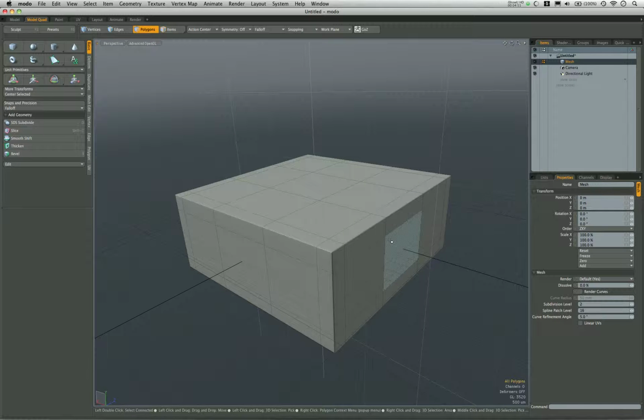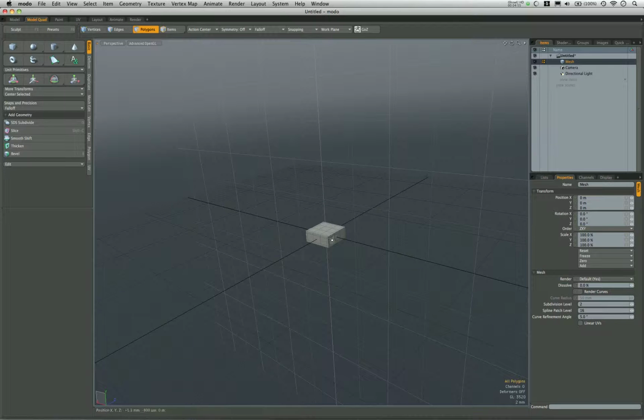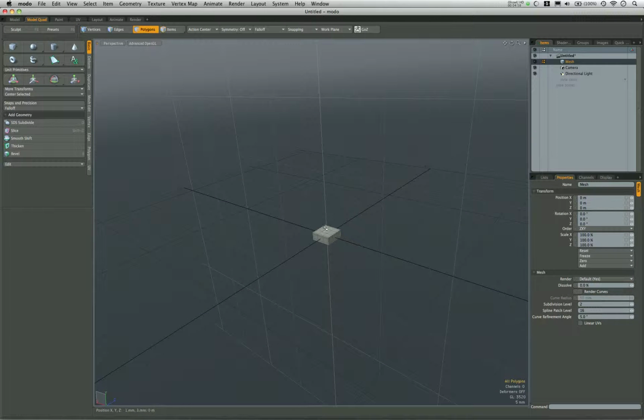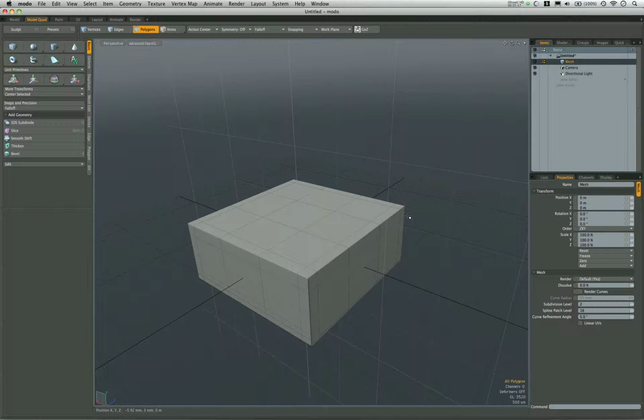But this will allow us, if we're unsubdivided completely, to still have a pretty nice look to our round section. So that's going to be important, because if we get this far out, or this far, where this piece is pretty small, we're not really going to need a lot of subdivision. But if we're only dealing with 4 or 8 sides, it's definitely still going to look kind of rough and segmented. With more sides, with a dozen sides like this, we'll probably have a much cleaner look here, and we'll have a look at that in a minute and see how that works.